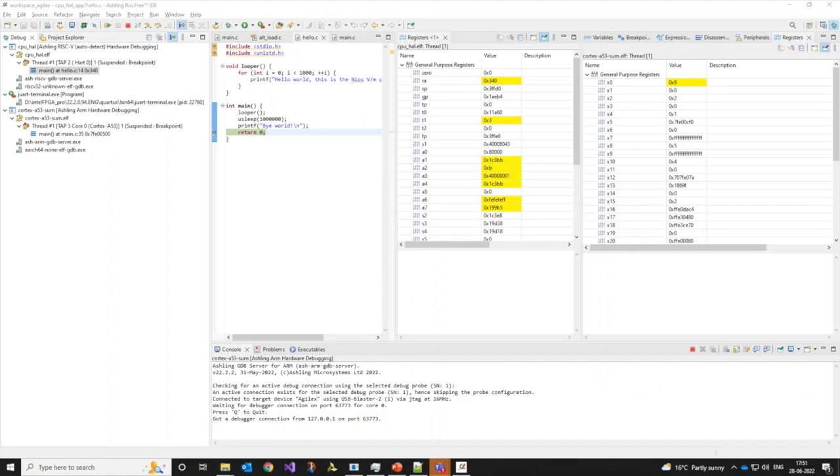I can answer that verbally while I'm typing the response in the chat. The system ID check is not integrated into the RiscFree tools like it was in the Nios 2 development tools. So that capability isn't supported in RiscFree, but the concept of using a system ID in order to keep your system coherent between hardware and software is still a highly suggested best known method of implementing a Nios 5 system.